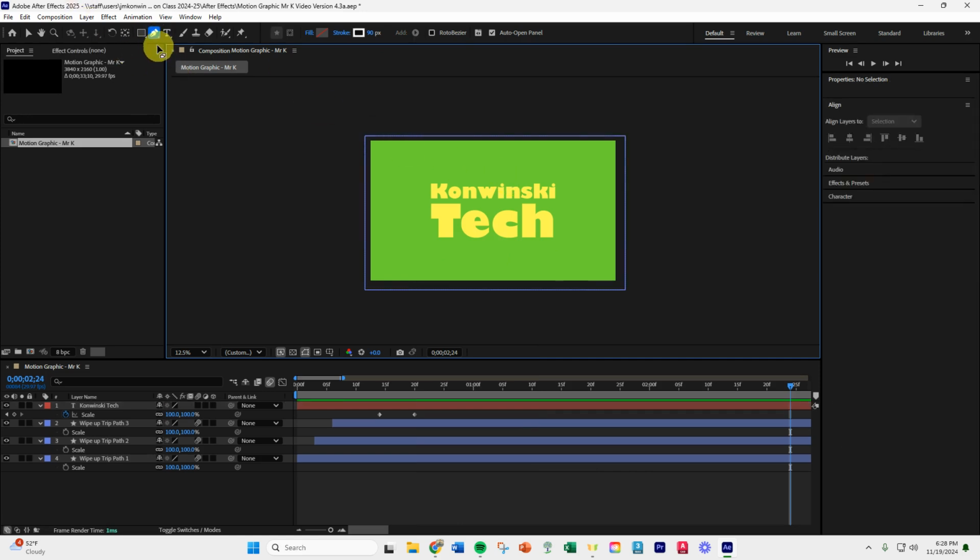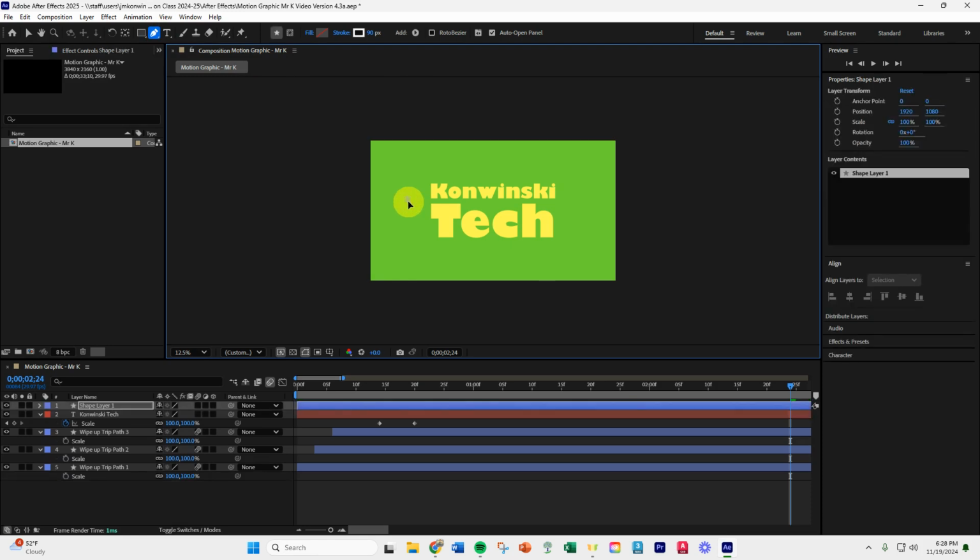And I'm going to start over and do it the way that I should from the beginning with my pen tool. So you can hit G on your keyboard if you'd like to just use the shortcut. So instead of clicking, what I'm going to do is depress my mouse and hold it and drag it out to get these handles a little bit. And those are going to tip the direction how the line goes, and it's going to control my curve. Those are Bezier curve lines. And I don't want to bring them out like this. That's way too far. So keep them nice and tight, and we can adjust them later.